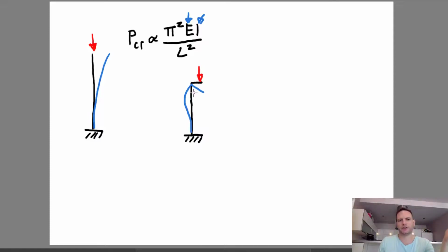And this gets really complicated because this is a nonlinear geometry problem. As soon as you load up this geometry right here, it starts moving in an appreciable way. Now, maybe if it's very small loads, you might not notice this, but when you're trying to design, when you're trying to save weight, which means things are not going to be any stronger than they have to be, these deflections start to really matter and really start to affect your design.